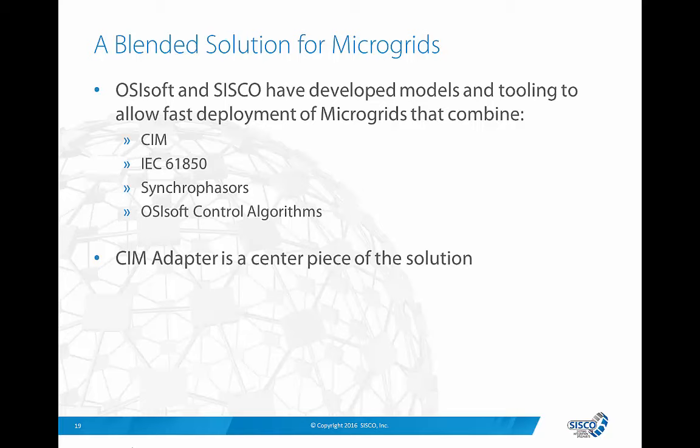SISCO is actively working with OSIsoft to provide a solution for microgrids. The basis of the technology revolves around CIM, the use of IEC 61850, synchrophasors, and OSIsoft developed control algorithms. As part of this solution, the CIM adapter is a centerpiece.